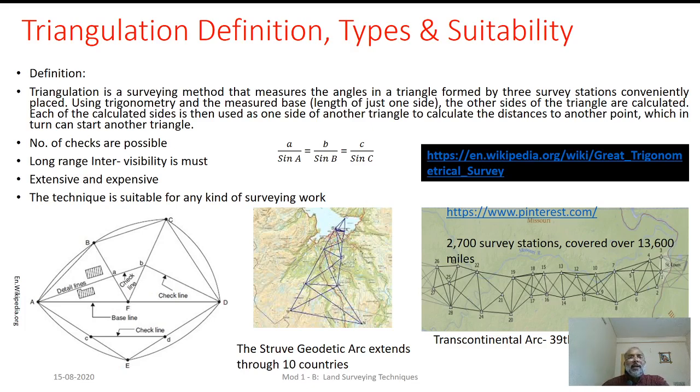So here we are supposed to divide the entire terrain to be surveyed into a number of triangles. For example, as shown in this figure, the length AD is the line which is running centrally through the piece of land that is to be surveyed.